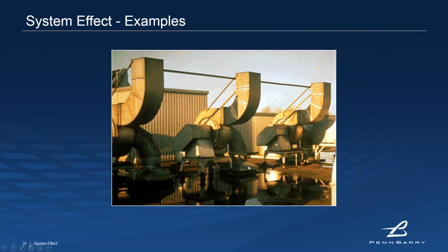They've done it a little bit better here. You know, they have a curve and they have this nice mitered corner. So presumably they have some straight duct down there. So that inlet condition looks pretty good, but look at this. We're taking an immediate turn. These elephant-looking fans are experiencing system effect as a result of that, where if the intended use here was really just to go up, all we needed to do was turn that fan 90 degrees and point it straight up. Problem solved.